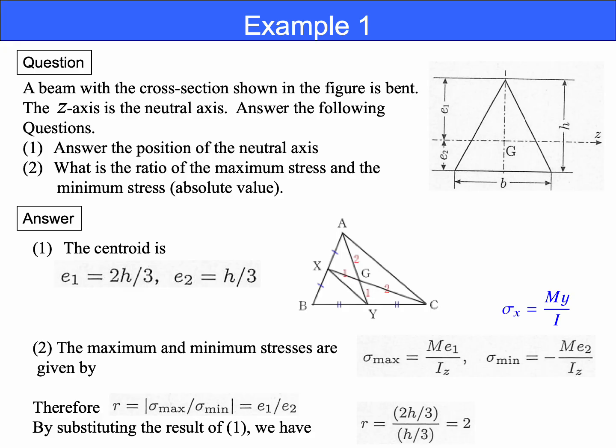So the stress at the apex side is twice the magnitude of the stress at the base side in absolute value, because the apex is farther from the neutral axis. Even if the cross-section is simple, asymmetry in distances E1 and E2 produces asymmetric maximum stresses.